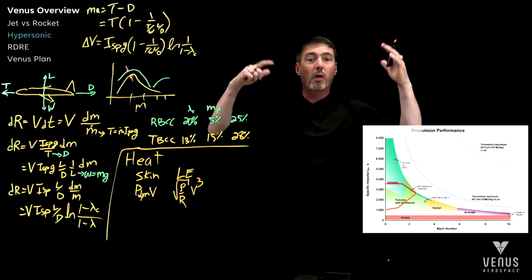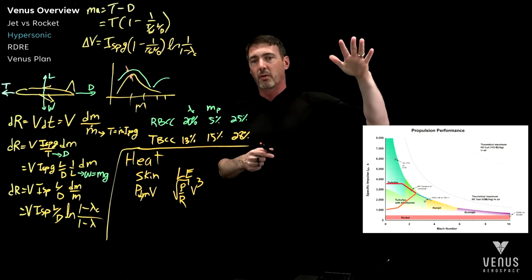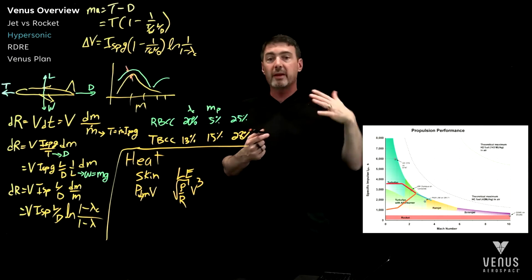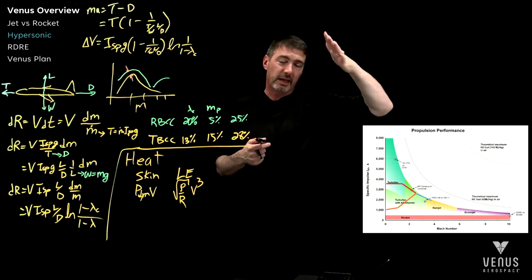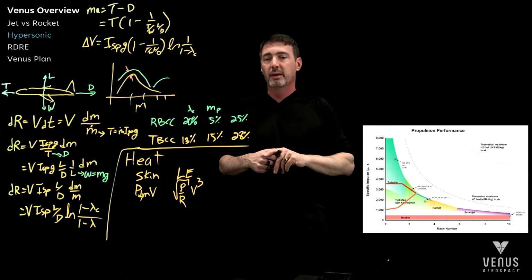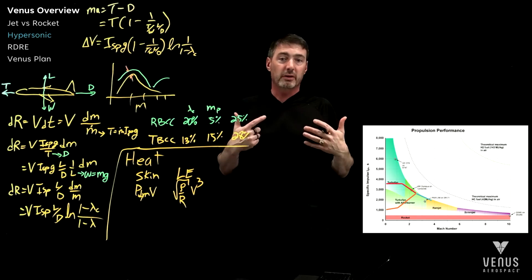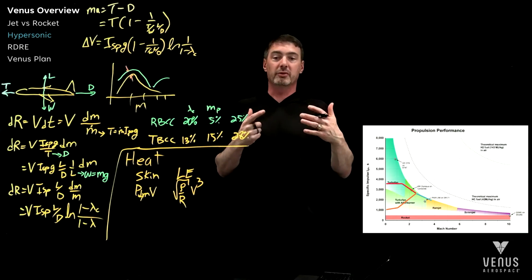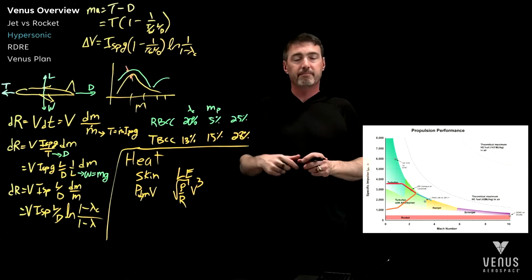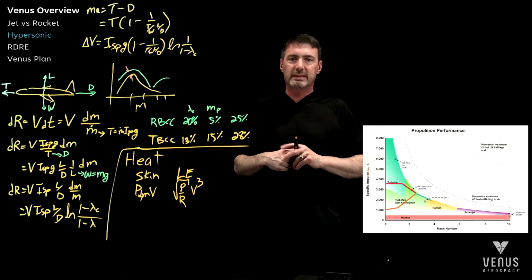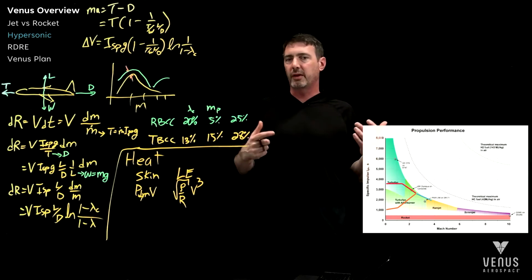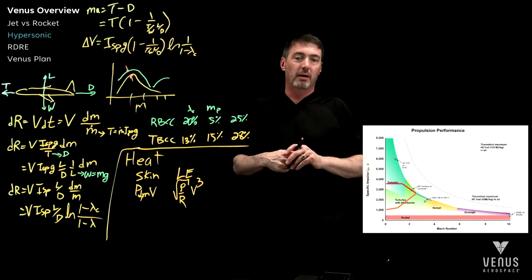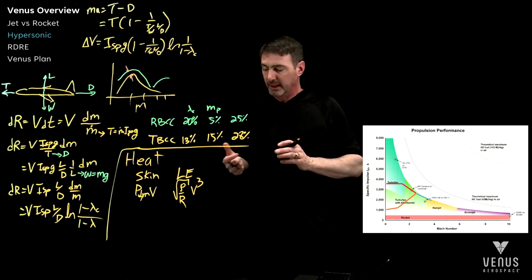So when you look at, say, the Apollo re-entry, or the Dragon re-entry, any of these re-entry vehicles that are really curvy, flat bottom, well, that's why they do it. There's a lot less heat when it has this big radius of curvature coming in. And so the same is true: blunt edges are going to be good for heat, but really bad for drag. So there's always this fight between the radius of curvature, the effective heat, and that drag. And so with some of the more advanced approaches, yes, there are higher temperature materials. You can also think through leading edge cooling systems that may help win that battle of drag versus heat on the leading edge systems.